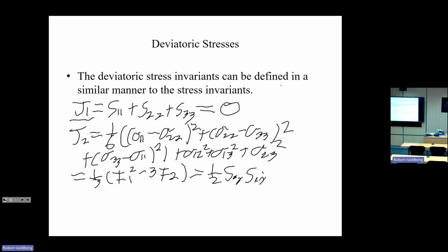the deviatoric stresses. And J2, if you look back at what you first saw in your undergraduate mechanics class and compare the definition of von Mises stress, you'll see the definition of von Mises stress is awfully close to this here, because the von Mises stress is directly related to J2. So J2, when you talk about yield, is a very important term.